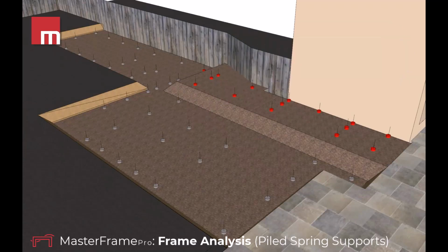Around the neighbouring properties, pre-coring was required to minimise vibration, and these are denoted by the red piles that we can see. And the contractor adopted a hit and miss sequencing for the temporary works for the installation of the ground beams closest to the neighbouring property to safeguard and avoid undermining its existing foundation.